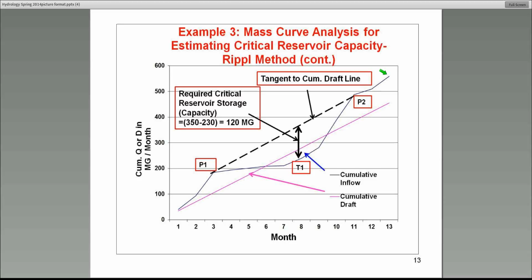This curve will start going down again and then going up, so you'll get another trough further down after 13 months, okay? You have to look at the P3 before you can actually call it a T2, a trough 2. So that's why it's called sequent peak. You have to identify another peak, P3, that's greater than P2. Since you're accumulating the inflows, that will always be the case.